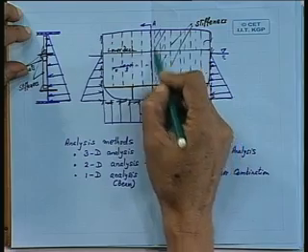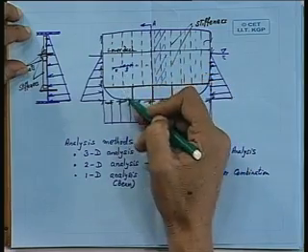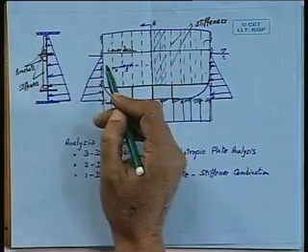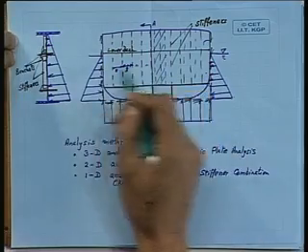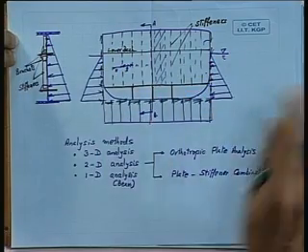So, if I am considering a strip out from here anywhere, the displacement or the bend shape which I get is identical for any of the strips. But in practice, the one which is towards the center will experience the largest displacement, and the one which is next to the shell hull will experience the minimum displacement.